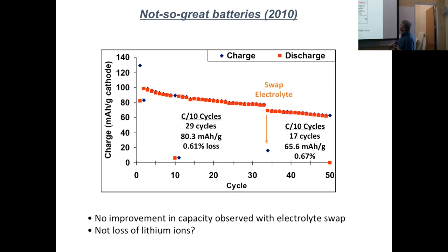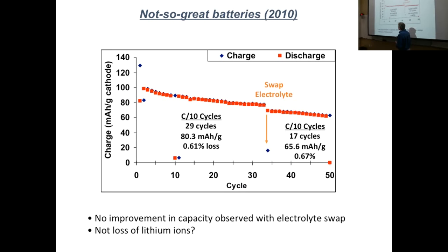So if we go back and say, well, how do we characterize the performance of a battery? There's lots of ways of doing that. The main way of doing it is simply to charge the battery and discharge the battery. Again, the first couple times you charge the battery, you use slightly different parameters, and that again is to make sure that this SEI layer forms very well and forms completely.